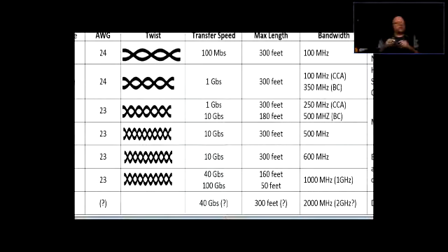Yes, it's better, all right? But if somebody has longer runs, like 200, 250 feet, and it doesn't take much to run that long of a cable, right? Then it just doesn't make sense to pay that much more money if those runs are longer than 180 feet because you're running basically Cat5e specifications, right?